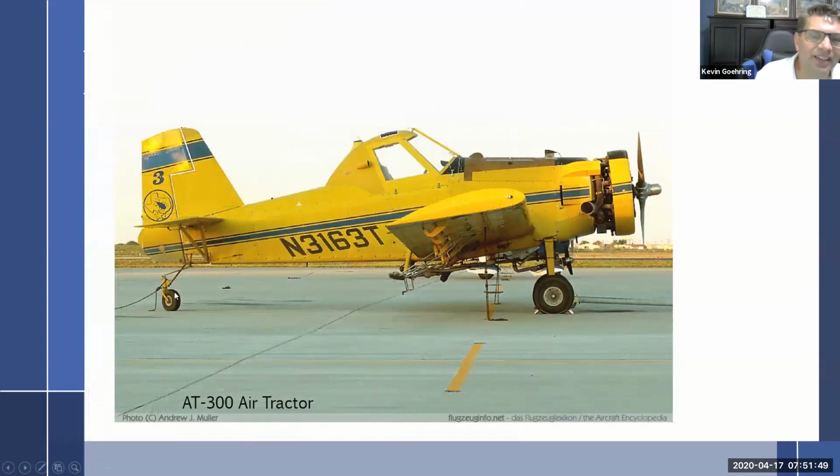Yeah, so see, like this one, it's wrapped, it's backwards. So it will unlock and swivel all the way back around. And so normally it's just spring loaded to the rudder, and so it's got some give and take. And then if you get it too far, it breaks away from that and you have no control over it. Some aircraft have locking tail wheels where you actually have to remember to lock it. If you don't, when you hit touchdown, it's kind of like a shopping cart and it'll go crazy back there and kind of go all over the place. So there's different kinds, but most of them are like the first type I described.